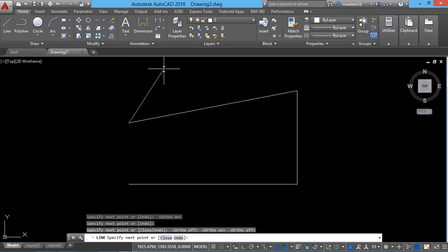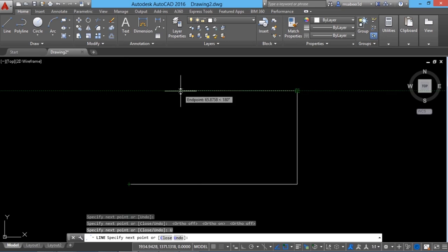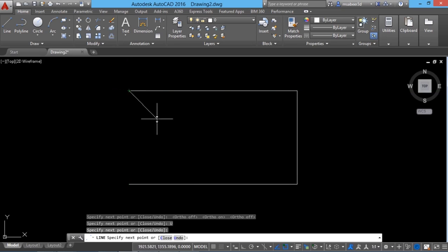Now I'll click a point here. Now I've got that point exactly on that vertical tracking line. I'll undo this. Now I'll track this endpoint once more, and I'll track this particular endpoint as well. Now when I move the mouse leftward, I will get the point of intersection. Now just make a click there. I've got that point of intersection.